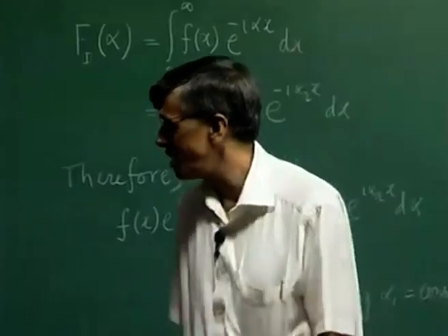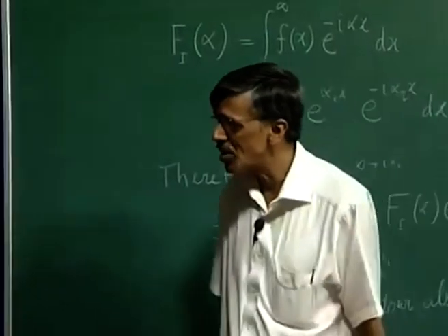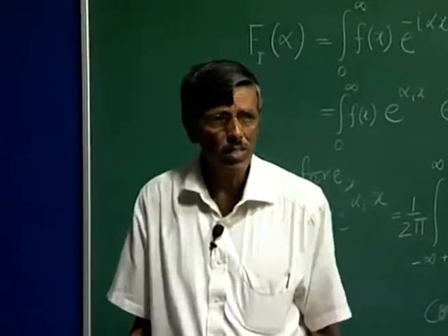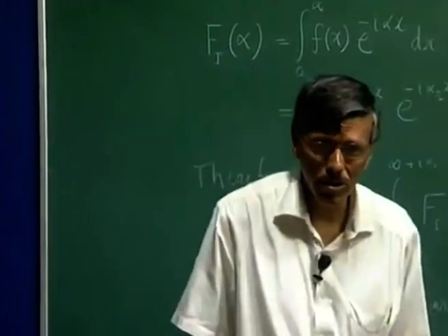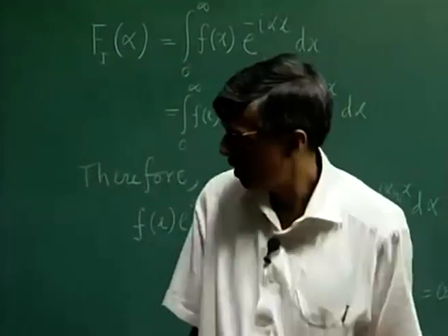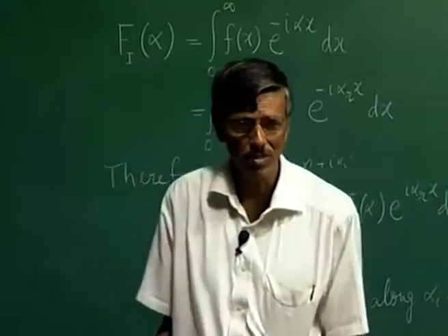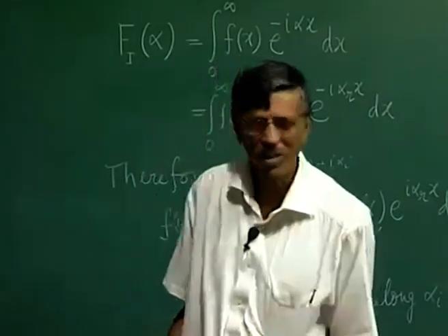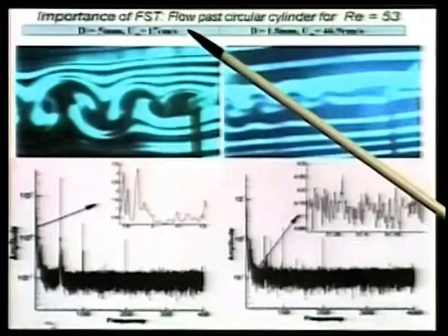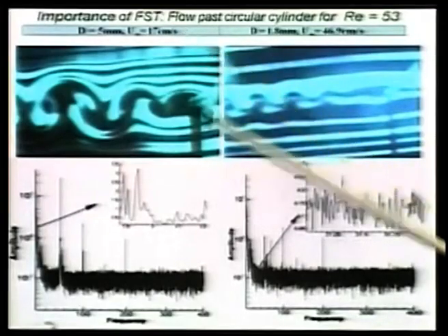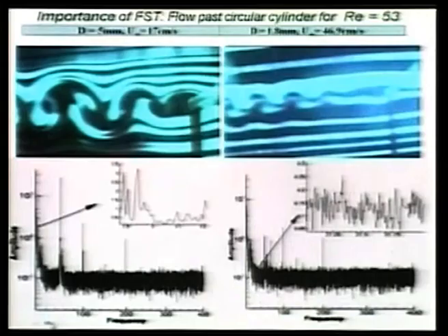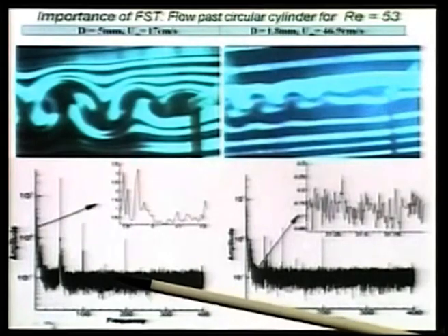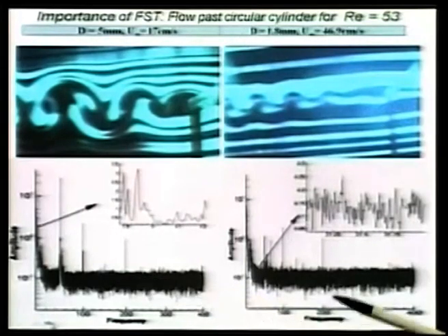What you can profitably do is try to find out the nature of the background disturbance in the tunnel. Well, the same tunnel should have the same background disturbance. Unfortunately, it is not so, because given a different speed, I get a different disturbance environment. This is what it looks like for 17 centimeter per second, and this is what it is for 46.9 centimeter per second, the same tunnel.